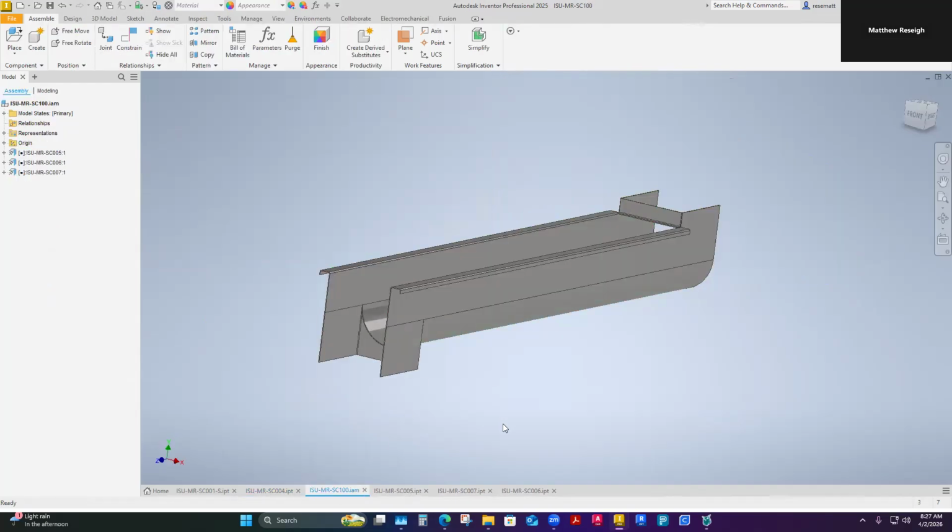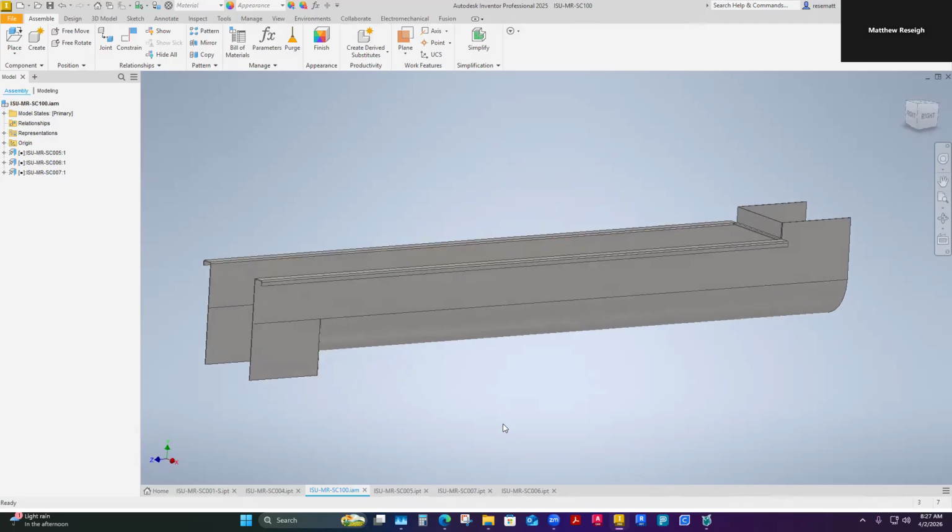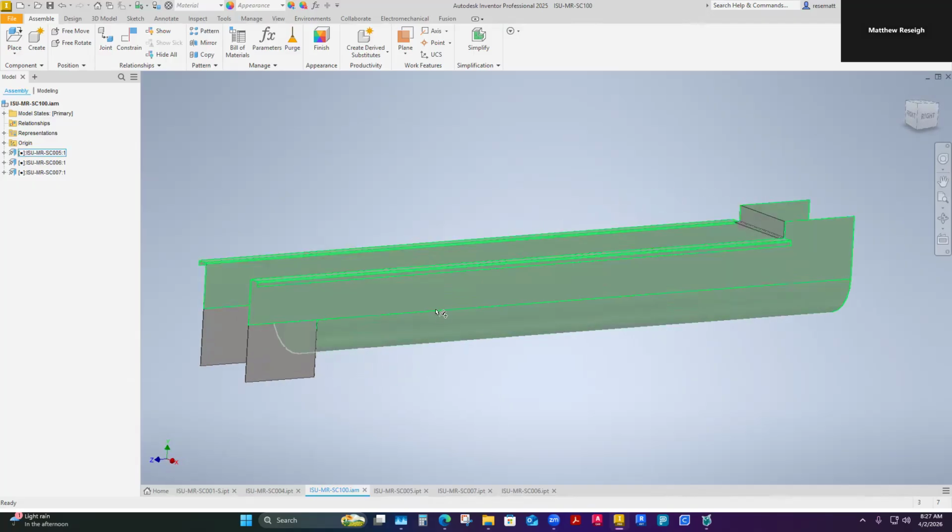Then once you click OK on that, after you've set your target assembly and given that a name, and then you've chosen which parts they are and given those names and chosen where they're going to go, then when you hit OK, it just sends you to that assembly, which for me would send me right to my .iam assembly that it created for me. And then from here, I can open up individual parts. It's kind of like grounding and rooting them in a way, right?